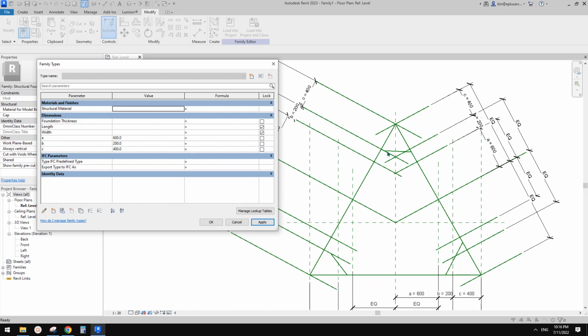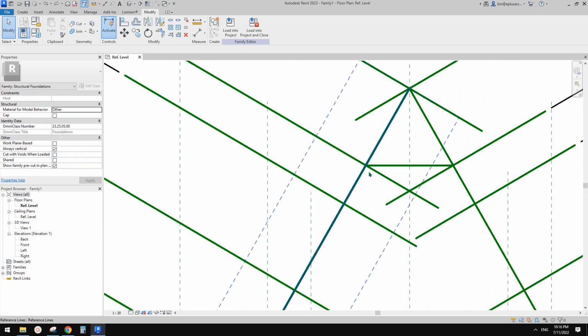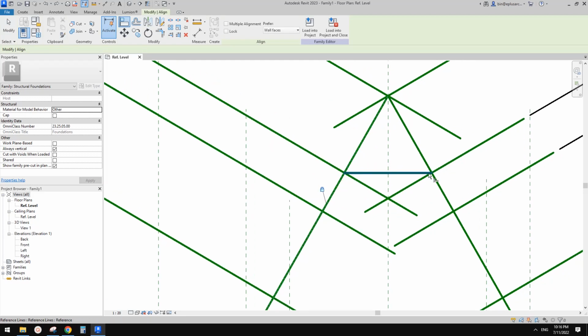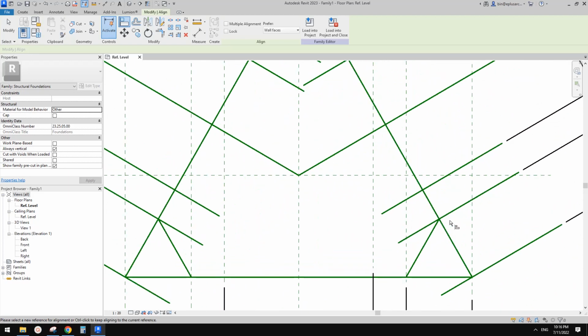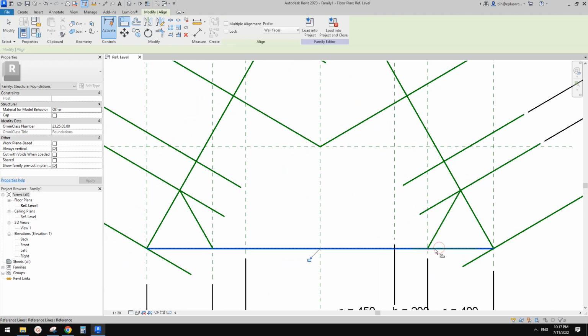The next step is we need to adjust this, and this. So let's cancel this, Control Z, go back, and then we need to align. So do the same, you need to lock this endpoint onto two references. Oops, not this one. Yeah, sometimes Revit will tell you over constraint. Just skip that. Okay, so you can see it's already constrained.